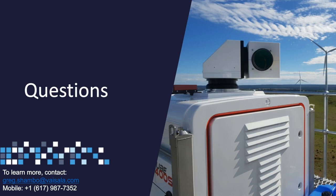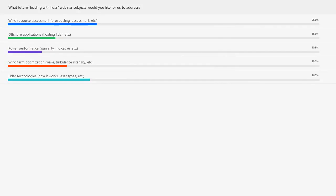Okay. And does the scanning LiDAR transmit the data directly to the end user, or do you have to go to the machine and pull the data? How do you actually physically get the data? Well, you can get the data either directly to an FTP server that you can configure directly in the software, or you can export it manually from the graphical user interface, or you can get it from an API request. And in this case, you will get NetCDF files or the data in a JSON stream. So that will be the end data, the raw data from the LiDAR that the user will get.